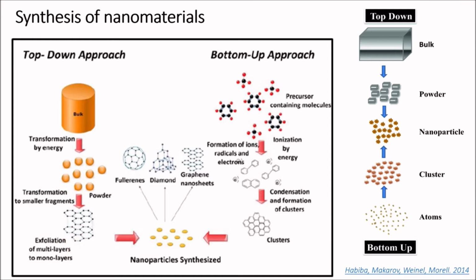Some of the examples are various lithographic techniques like ultraviolet, electron beam, X-ray, focused ion beam lithography, etc., and various milling processes. Top-down refers to the traditional workshop or microfabrication method, where tools are used to cut, mill, and shape material into the desired shape and order. The biggest problem with the top-down approach is the imperfection of surface structure. For example, the nanowires made by lithography are not smooth and may contain a lot of impurities and structural defects